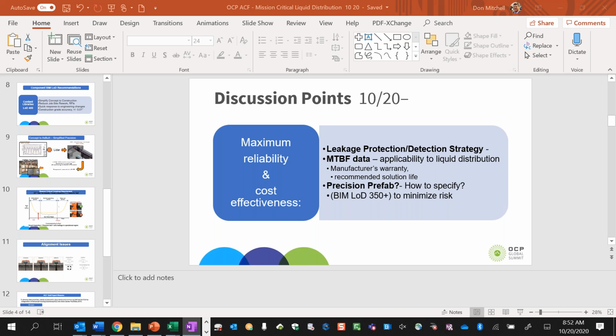One way we thought we'd mitigate that is to diaper that joint or that valve, and then put a moisture sensor in that. That would be a relatively simple solution, and we actually decided not to do that. Further analysis showed that all our water was in the hot aisle, and a spray or leak would not impact our servers or compute devices for the most part, because it would spray into the hot aisle and be found on the floor or felt walking by it. So we abandoned the diaper, but it is a clear solution if you have a really critical path: put a diaper around the valve and put the sensor in that.